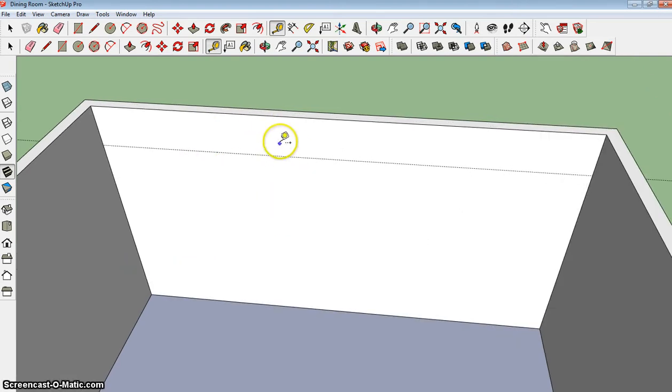Now the reason we're putting some distance between the ceiling and the top of the window is because structurally engineers have figured out that we need a header over the top of the window. And so the weight of the second floor, the roof, is pushing down on this wall. It hits a structural member called a header, and then distributes around the window down through a jack and king stud, and then around the other side down through a jack and king stud into the foundation. So we're going to kind of simulate real construction techniques here. So 80 inches high, almost anything else goes.